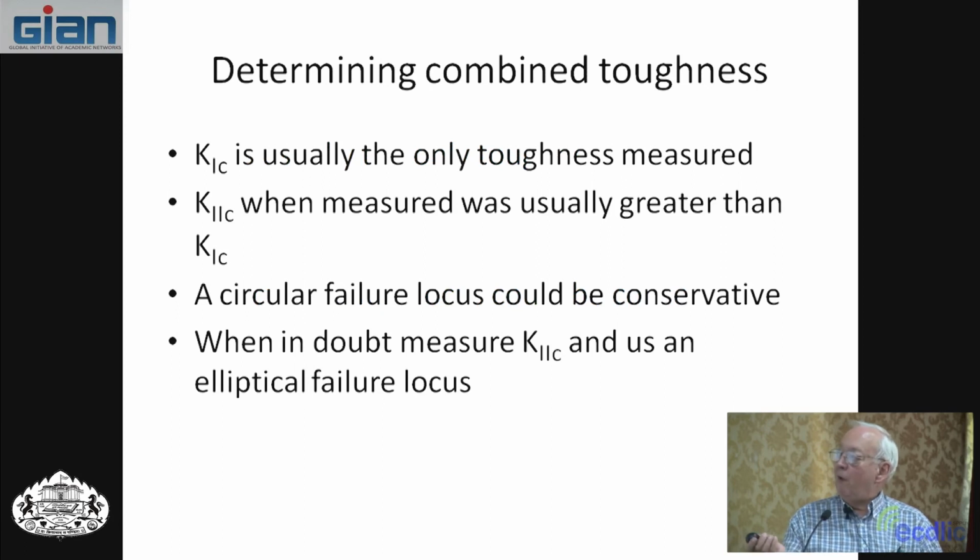Now, if you want to do fracture toughness, there is a problem in that people have done a lot of K1C measurements. K1C is often measured. K2C is not often measured. People try to make K2 tests, and they've done that successfully, but not many people do it.